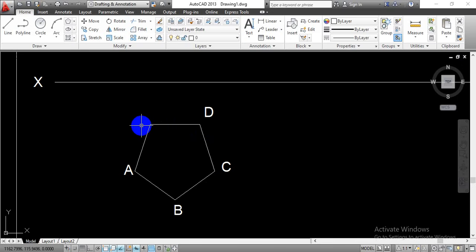Now once we are done with this, we have to find the center point so that we can have the apex O, and with respect to that apex point O, we can connect all these base corner points by the generator lines. To have that, let me go with the line command.